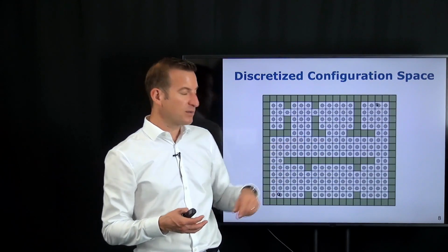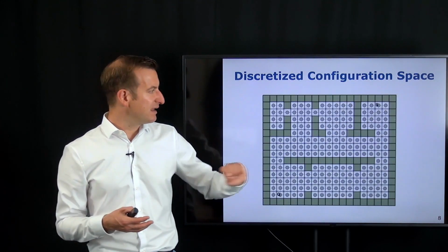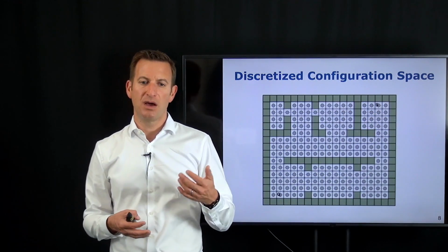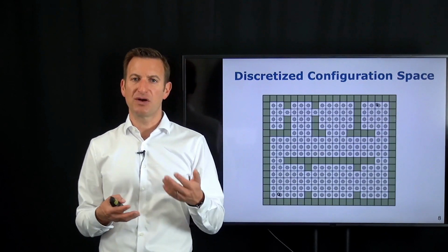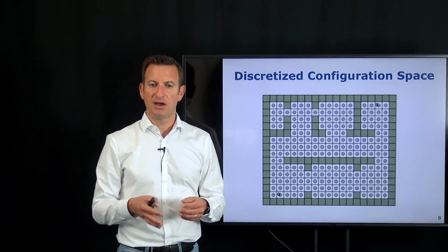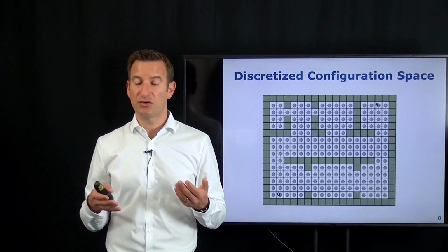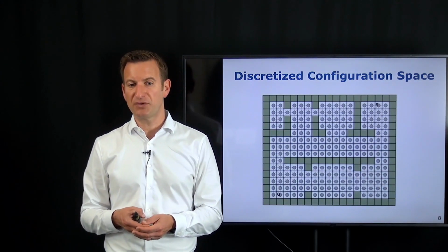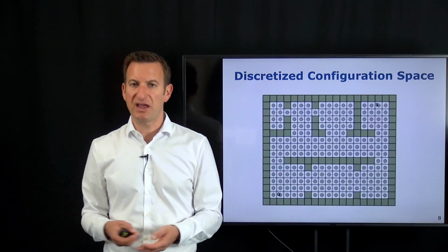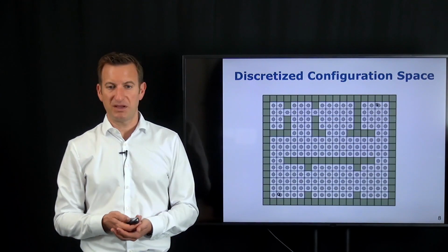And those dots are connected with each other depending on the connectivity in that map. By finding a path through that graph, for example, from a start location to a goal location, we are able to describe how the system should move through the environment. Often this happens in this discretized space. It doesn't have to be discretized, but quite often we are working in discretized spaces because the continuous space is very tricky to represent, and it may not be a uniform discretization as it's done here. Also, sampling-based techniques are another alternative to subsample the possible states the system can be in.